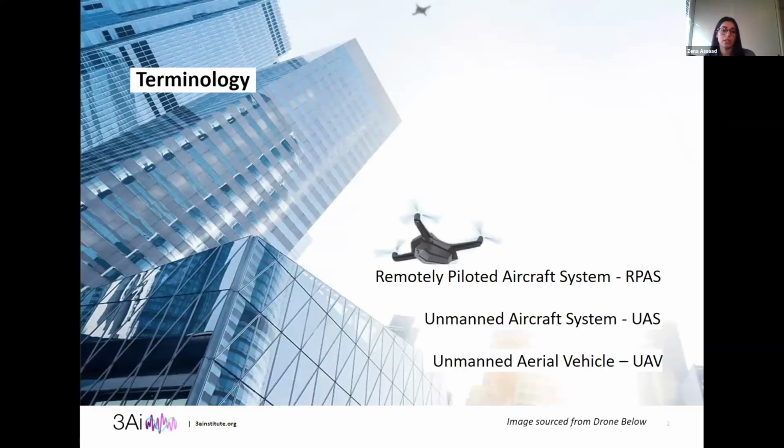So I wanted to start by just going over some basic terminology that's often misused or used interchangeably, particularly in the aviation space. I'll start with automation and autonomy. Automation and autonomy are constantly used interchangeably, but they're actually not the same thing, and they're quite different. Automation refers to the execution of a predefined task performed without human assistance. It's deterministic, the outcome is known. Whereas autonomy refers to performance under significant uncertainties within an environment. It's non-deterministic, and it requires decision-making without human assistance that may result in a range of possible outcomes.